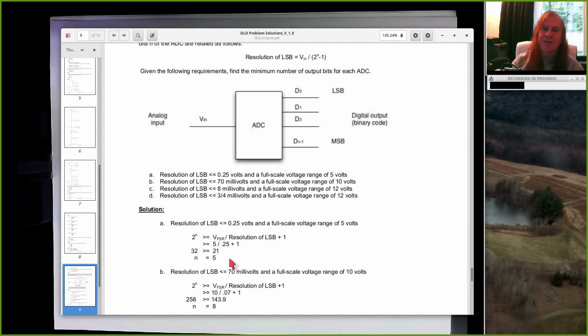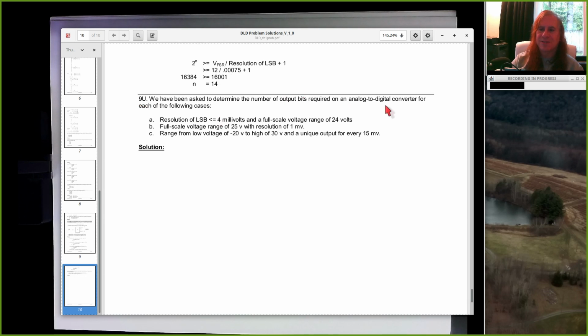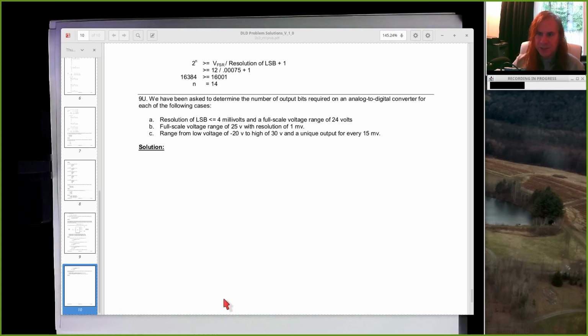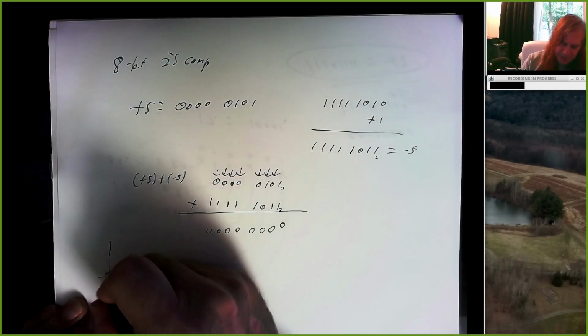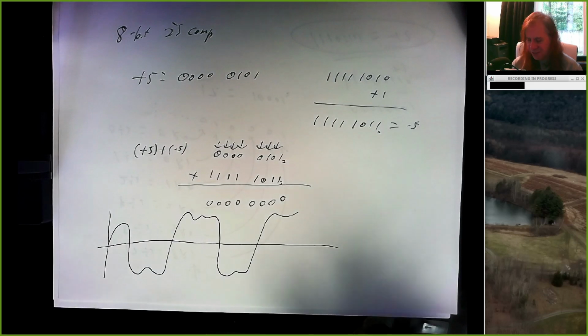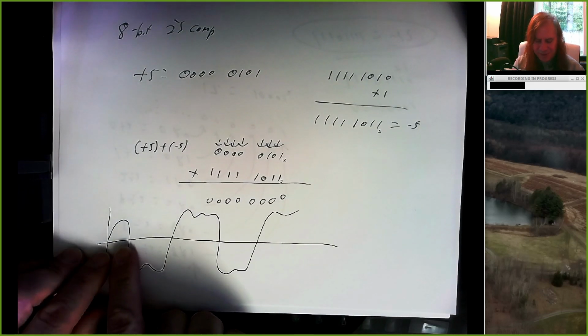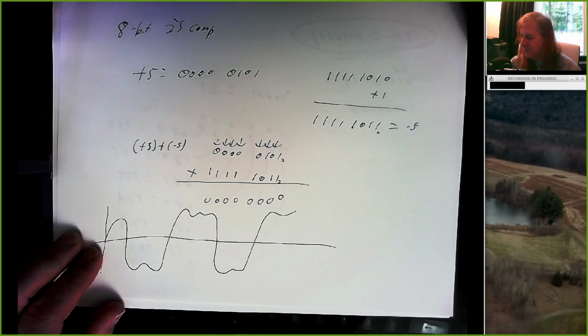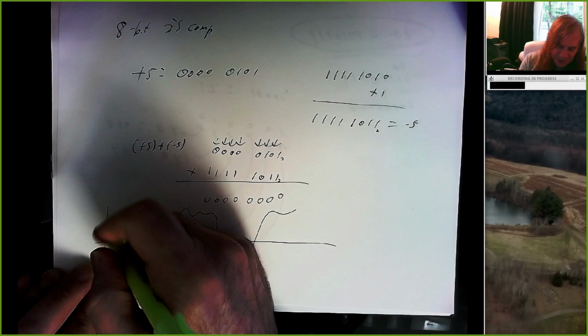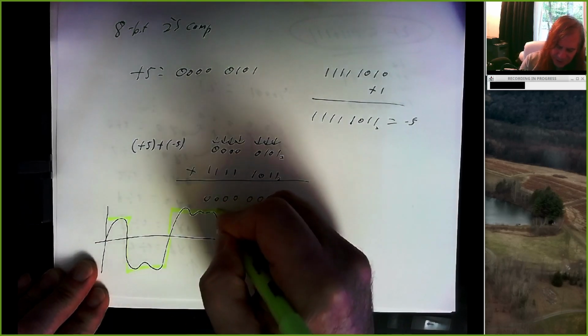All right, so the one that we haven't gone over that we need to talk about is analog to digital conversion. We started off in the beginning of the course looking at this idea that if you have a waveform which is analog, so something that has values that could be positive or negative, we could approximate this by saying, for example, everything above 0 is going to be treated as a logic 1, or a high voltage level, and everything below 0 is going to be treated as a different signal. And so we might do this to approximate this waveform.